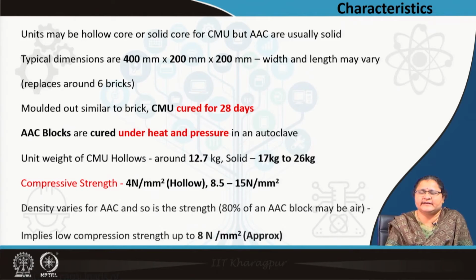So, you can well understand it is at par with brick, but having larger coverage, fewer joints, faster construction, and less water absorption. You can even avoid the plastering part if it is a dry area.